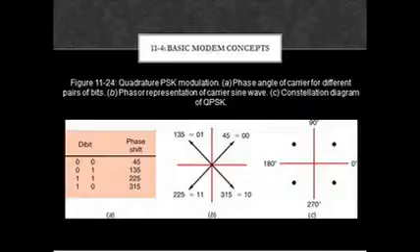One commonly used system for doing this is known as quadrature or quadriphase. In QPSK, each pair of successive digital bits in the transmitted word is assigned a particular phase as indicated in Figure 11.24a. Each pair of serial bits, called a dibit, is represented by a specific phase. A 90-degree phase shift exists between each pair of bits. Other phase angles can also be used as long as they have 90-degree separation.